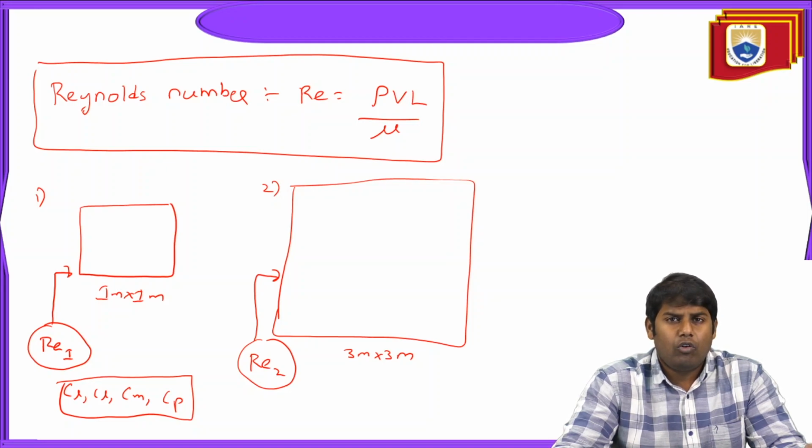Let's say you have a low speed wind tunnel with incompressible flow. It has a very small test section. For the small test section, we will use small models. In the numerical simulation, we can go for the actual or the large models. We can compare the experimental and the numerical results when we equate the Reynolds number.